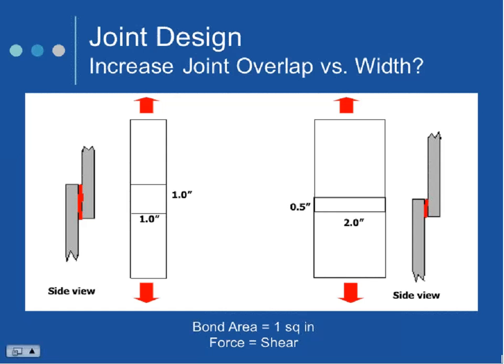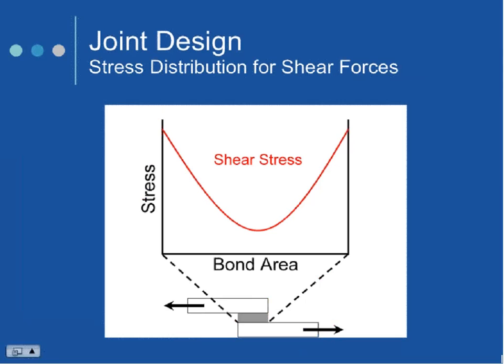So let's back up and take a look at this slide. Remember, the leading edges are what are giving you that support. So what you might think is, let's just say you get 1,000 PSI bonding stainless steel to stainless steel. I know when I first started with the company, you might think, well, if I double the overlap, then I'll get double the bond strength. It just doesn't work that way, because you haven't changed the geometry of these leading edges or ends.